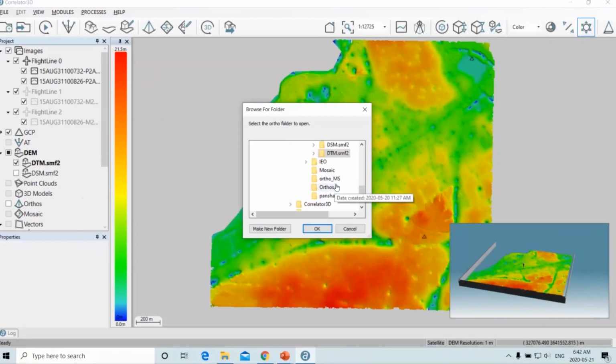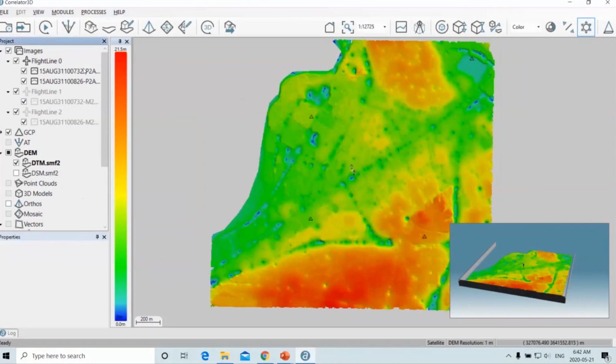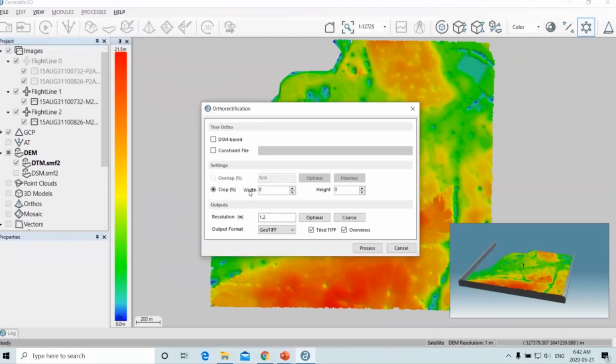So here what you can see is I did one folder for the ortho panchromatic, and I've created another one for the multispectral. And then once you have changed your folder, you will be able to disable your panchromatic images and then re-enable here your multispectral imagery. And when you generate the ortho photos, I see that my resolution has changed, which is now the resolution of the multispectral imagery. So at the end here, the goal is to have two different sets of ortho photos.